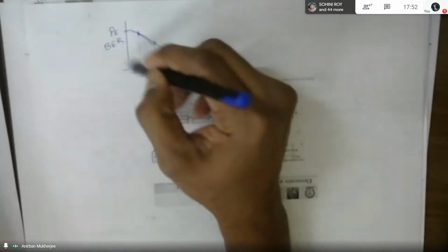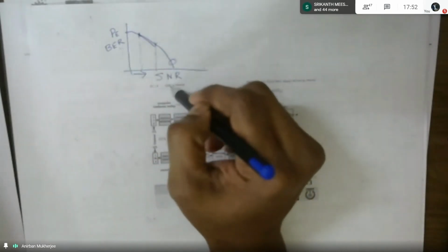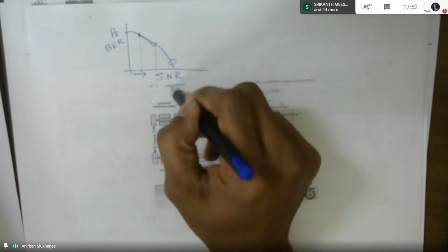So channel coding for a given data rate can reduce the probability of error, or reduce the required signal to noise ratio to achieve a desired probability of error, at the expense of transmission bandwidth or decoder complexity. Okay. Now sometimes this is one option. Sometimes we say no, I will not. So this is one trade-off: probability of error versus your SNR.